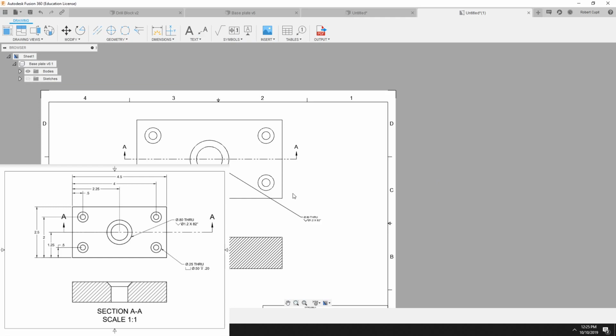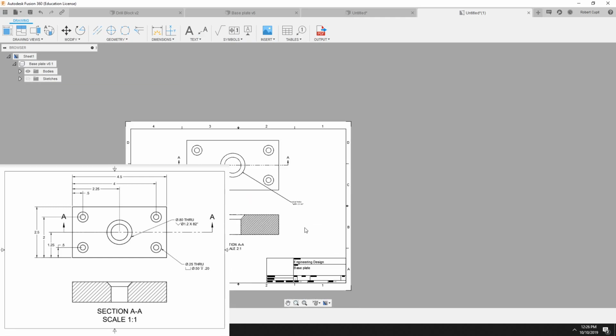After that, you can realize that the text is way too small. You come down here to the gear, change the annotation text height to 0.24. Now we can all see what's going on. You submit this as a PDF for all 2, and you're good to go.